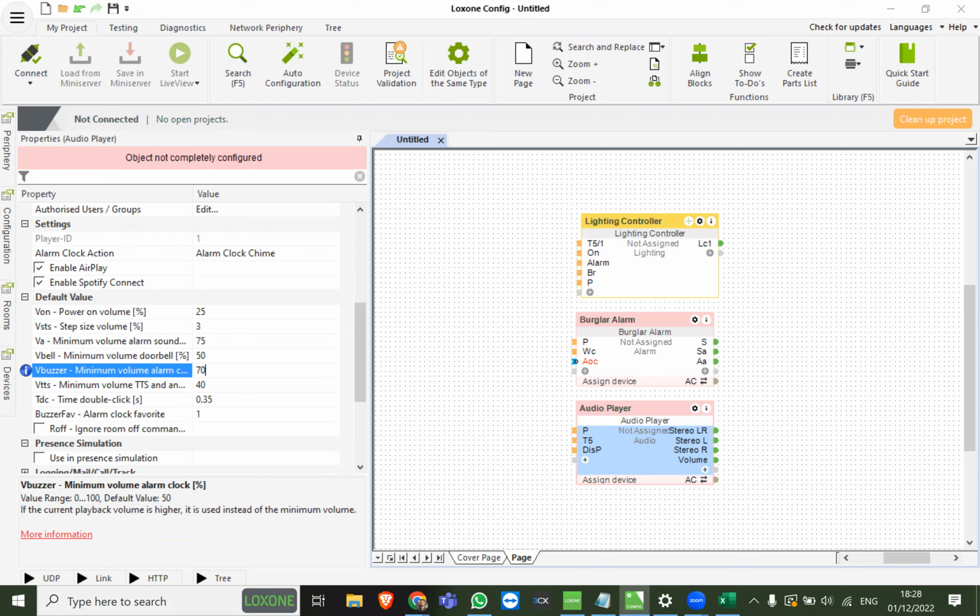You're not going to trip anything. If you want, for your own peace of mind, have a little bit of wiggle room, that's absolutely fine. But don't have 100 amps worth of wiggle room, have maybe 10, 20, just so you're peaceful and you know that maybe in the future, if I want to add a few more lights, if I want to add a few LED strips, I'm not going to be desperate for power and need to buy another power supply. I have enough on board already.